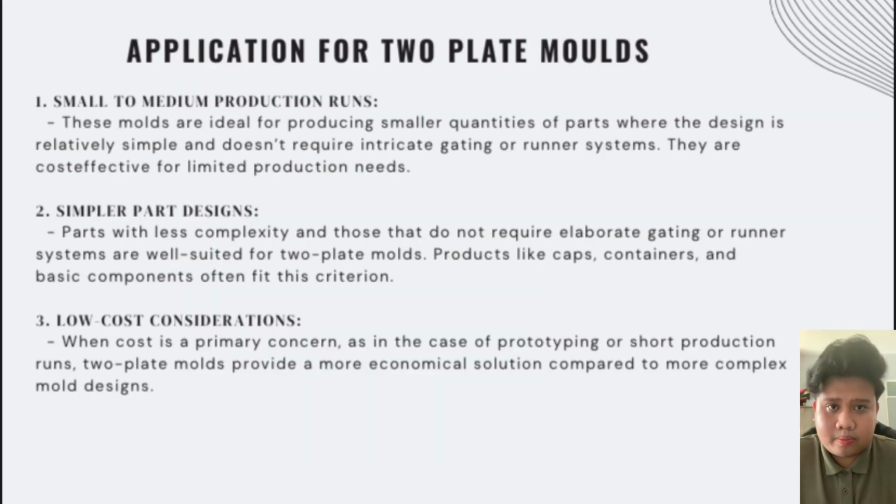Applications for 2-plate molds. First, small to medium production runs. These molds are ideal for producing smaller quantities of parts where the design is relatively simple and doesn't require an intricate gating or runner system. They are cost-effective for limited production needs.